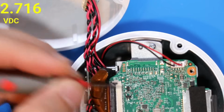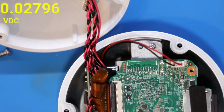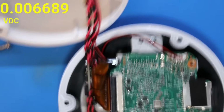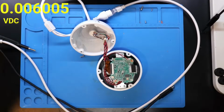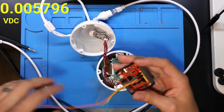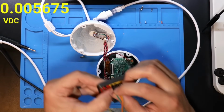Another thing we've done at the same time is confirm that the voltage of this UART line is 3.3 volts. So I'm going to go ahead and power this device off, and we're going to get our UART interface set up. Right here, I need to plug these in.